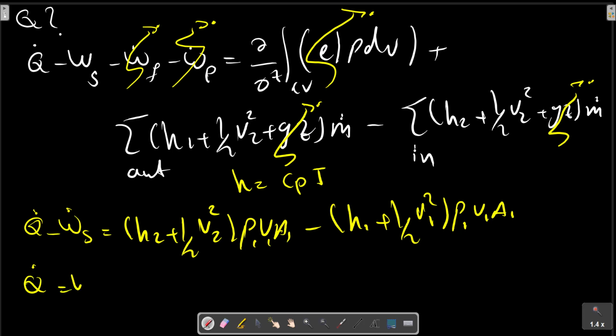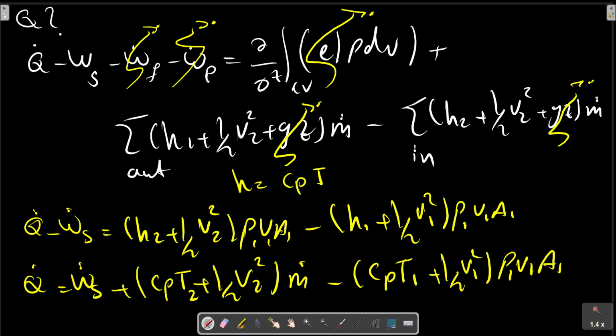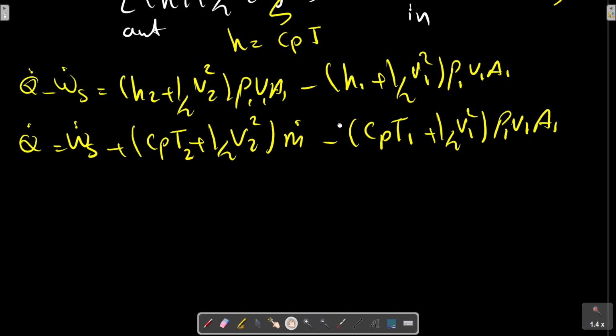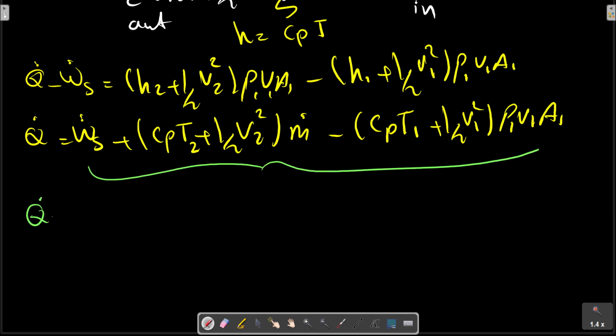So Q dot equals W dot S, which is known, plus m dot Cp T2 minus m dot Cp T1. With replacing the quantities of these parameters, we can calculate Q dot equals ... BTU per ...